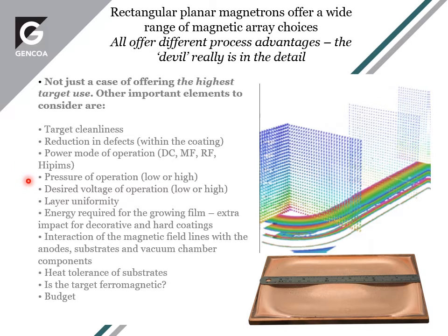Pressure of operation: some processes you want to run at low pressures, you need very strong fields. Equally, if you're running at high pressures, you need weaker fields for various reasons. Voltage of operation, similar. Strong and weak fields help that. So if we want a low voltage operation for, say, sputtering TCO materials such as ITO, then again we tend to go towards the high strength field.